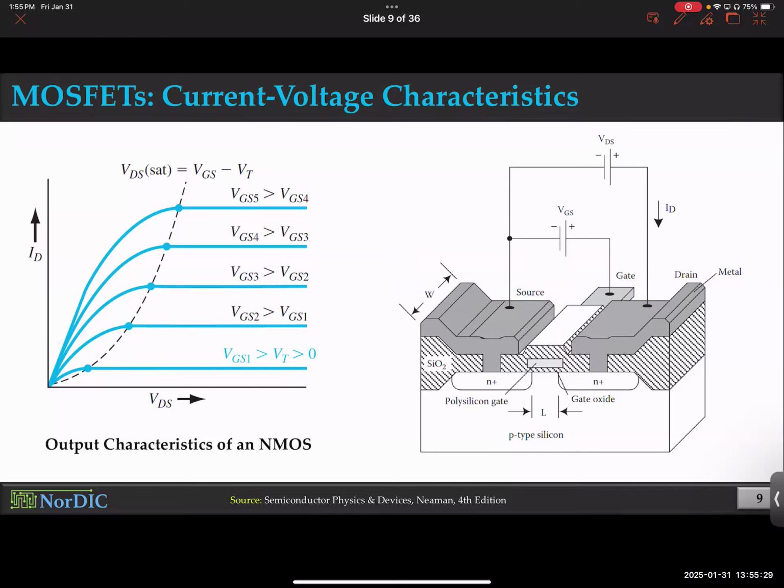So in the last class, I discussed output characteristics, and then I discussed transfer characteristics. I don't think I mentioned the name transfer characteristics, but essentially I talked about the ID-VDS characteristics and ID-VGS characteristics, right? So very quick recap. If you have a transistor with gate, drain, and source, you need to look at the drain to source current, which we just represent as ID, or we could have written IDS, doesn't matter.